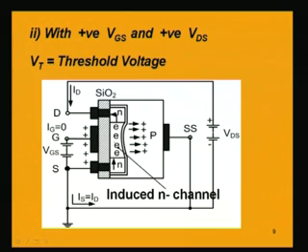As these majority carriers, which are holes, are pushed deep into the P type substrate away from the insulator, around this insulator there will be a depletion region, because in this region the acceptor ions will be just surfaced out, which are the immobile charges.